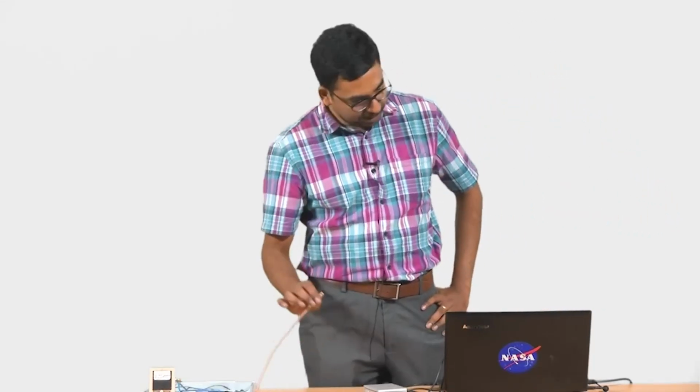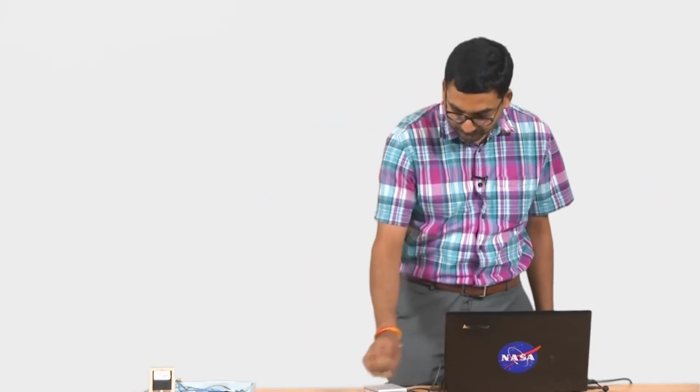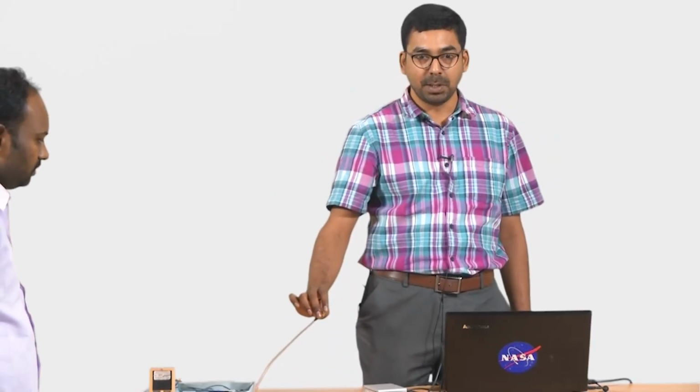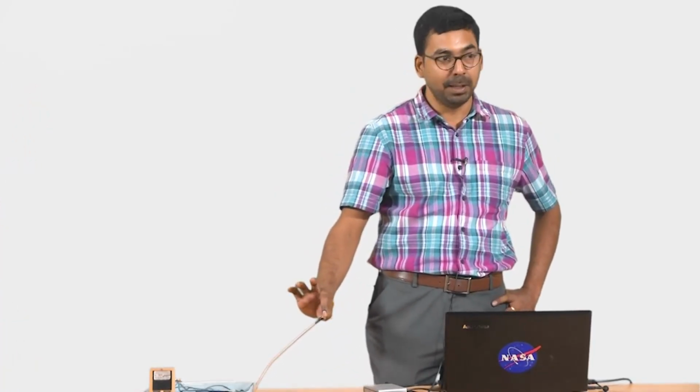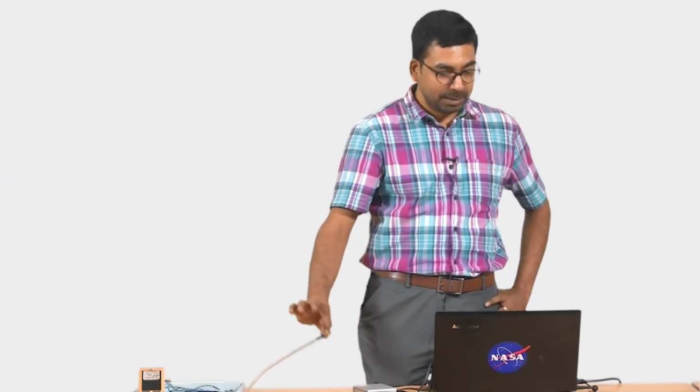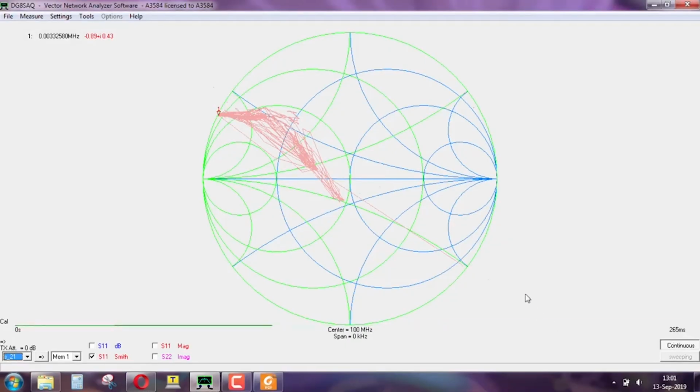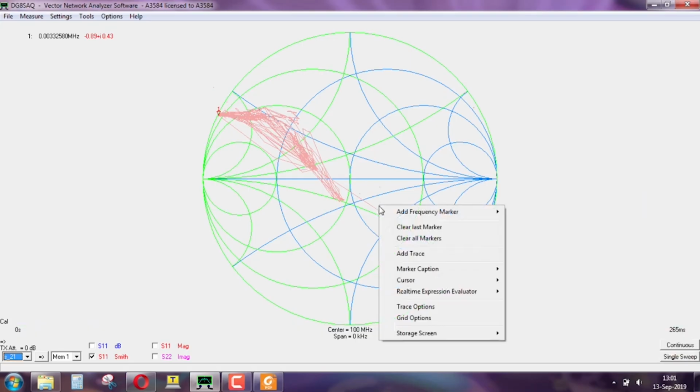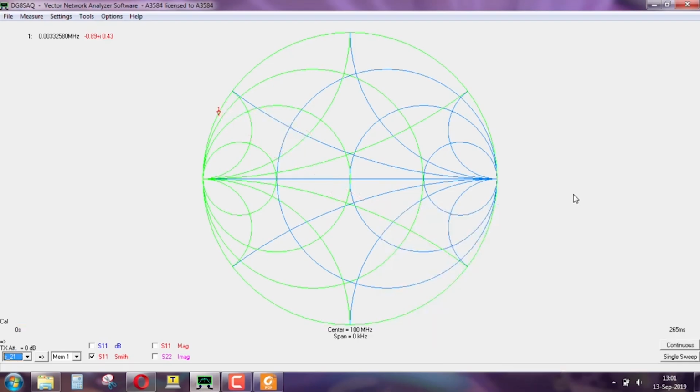There was something we did with open circuit and short circuit, right? Currently, I think the transmission line is open circuited. This was a question that was asked here: I want to determine the characteristic impedance of this open circuited one, and then you have to find out the impedance. You can notice that it's not on the horizontal axis. It's having a small amount of inductance.